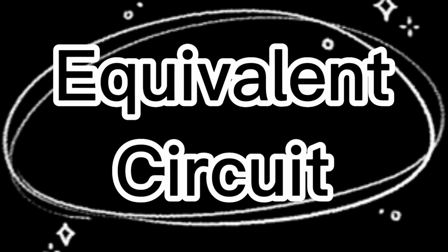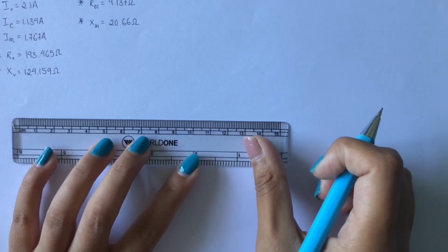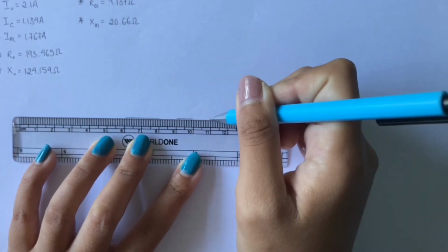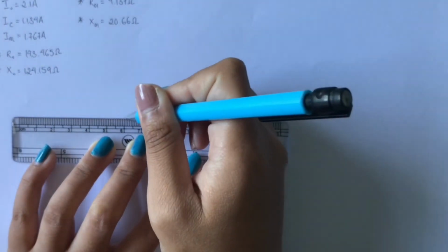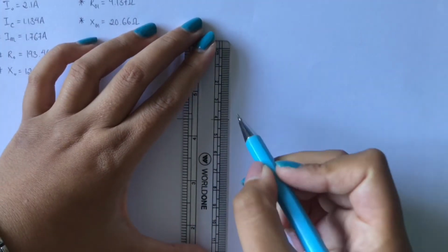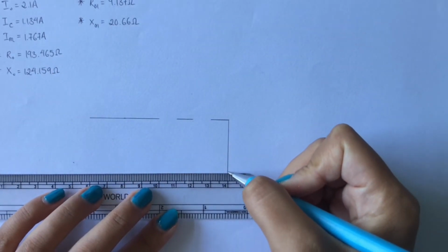We can now draw the equivalent circuit. The parameters we need to draw the equivalent circuit are the resistance and reactance of the no-load and blocked rotor tests. We also need the no-load current, magnetizing current and active current of the no-load test.